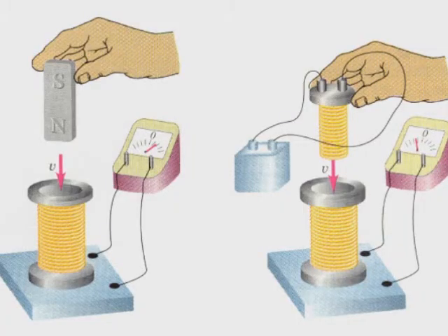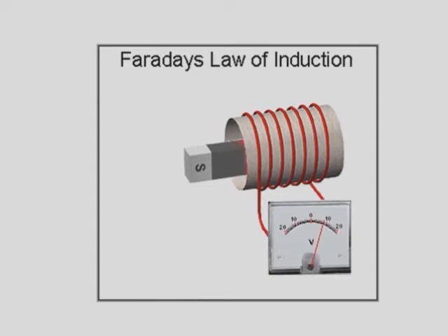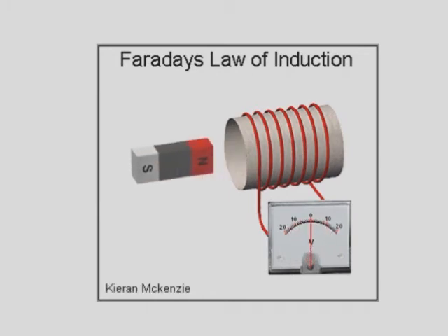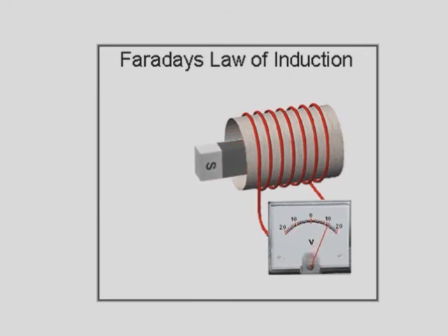He performed his experiment by moving a magnetic bar in and out of the induction coils. Here he observed two things. First, when the flux linking a loop or turn varies with time, there will be an induced voltage between the terminals. Second, the value of the induced voltage is directly proportional to the rate of change of flux. In other words, if induced voltage is increased, rate of change of flux will increase too, and vice versa.